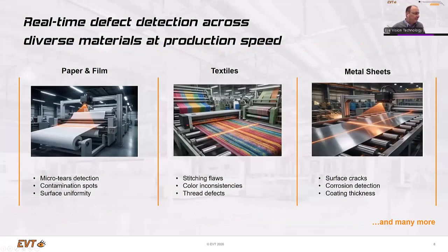Here are, as I mentioned at the beginning, some examples from metal sheets to fabric and non-fabric, woven, non-woven material at the end. And even if you have woven material, the line scan camera is the much better option, because you don't have to deal with the complete image while the production line is running. You concentrate on the position where you do the inspection and generate a clear view of all the defects.